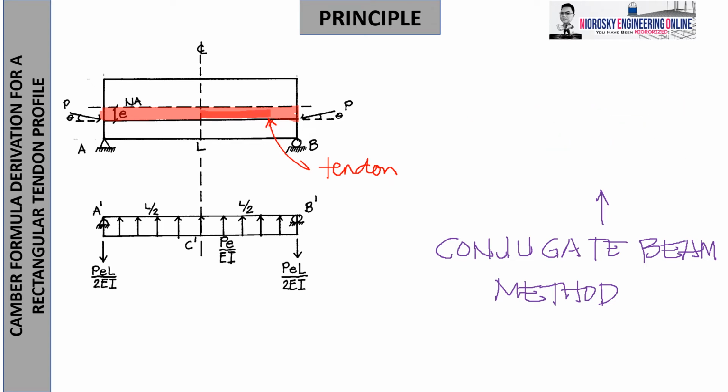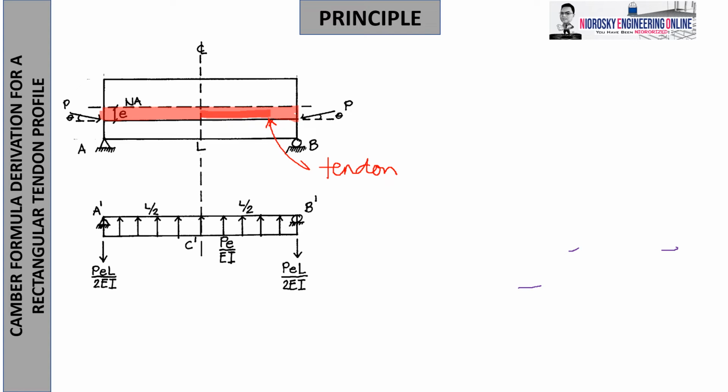So, again, let's take a closer look at our calculation. Here we can see that our load is upward, fictitious, because that is the effect of this, since it will compress. Mark in violet. The pressure is upward because it will push upward. So that becomes our fictitious load. If you recall the conjugate beam, you take a moment, which is simply P times E, that is why it is over EI. Remember, the hallmark of the conjugate beam method is dividing by the flexural rigidity EI.